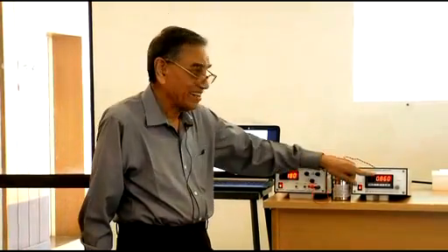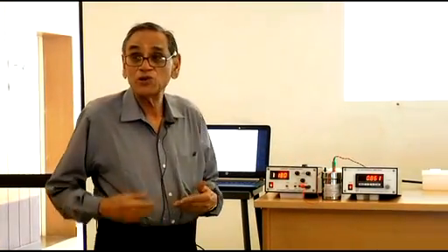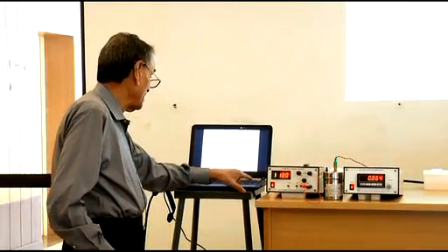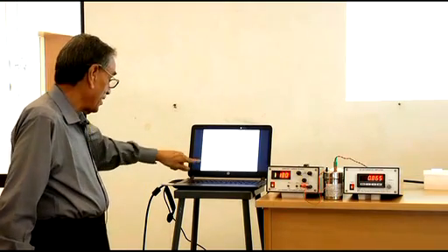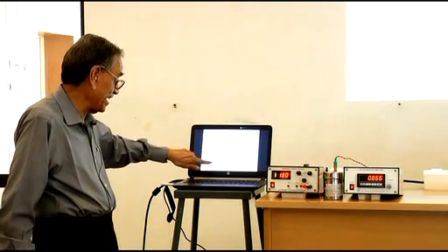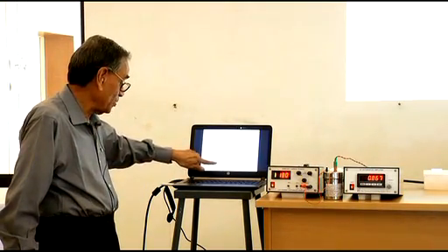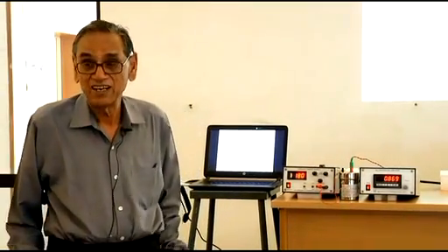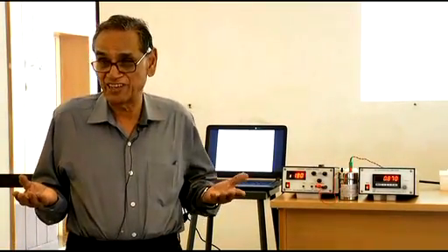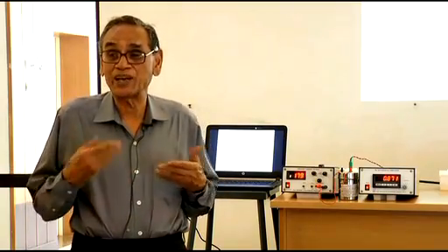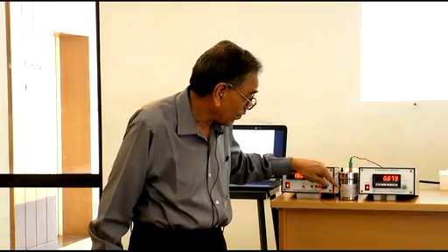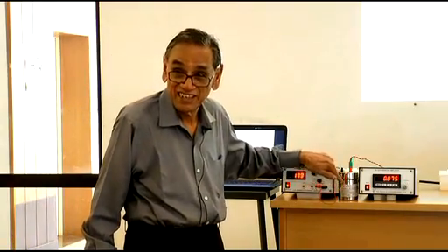Then note the current and this reading. You keep repeating this for different currents of 200, 180, 160, 140 and 120 milliamperes. Note the room temperature and convert it to Kelvin by adding 273. That is the temperature T2 of this stainless steel box.